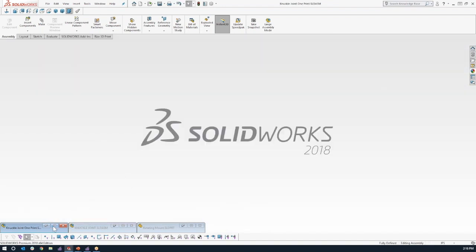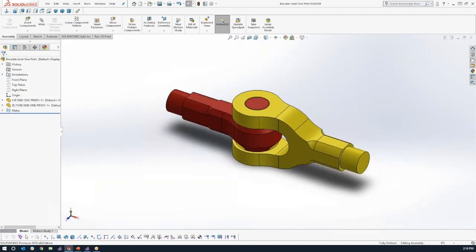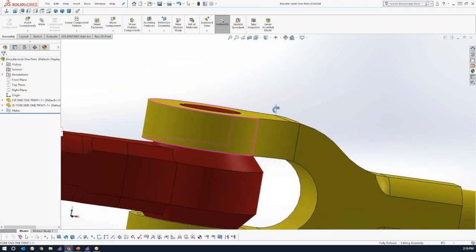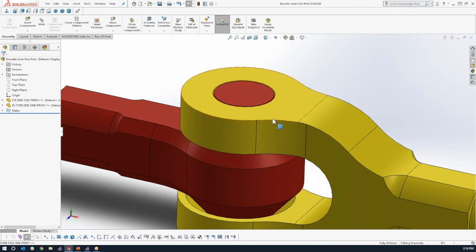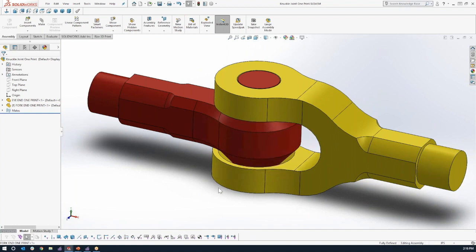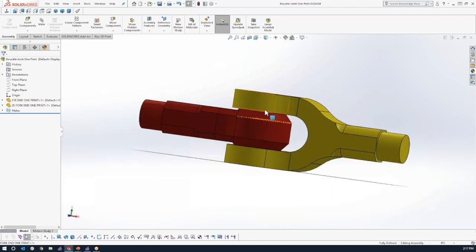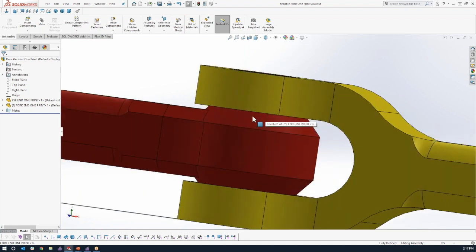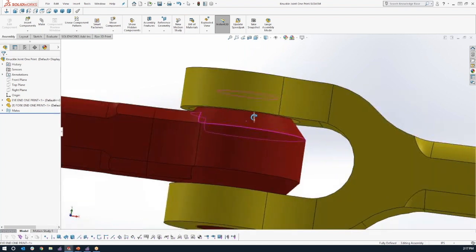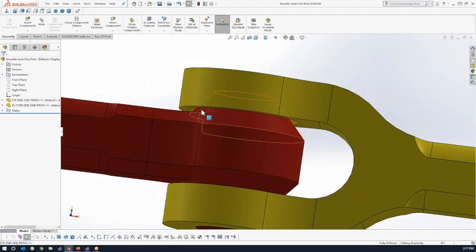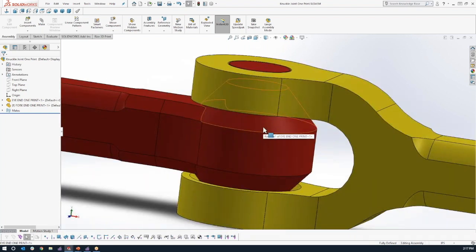Another approach is actually to design them so that you can print these parts as a single piece. Not only will it reduce the number of components that you're using, but you'll be able to print it in its flexible form right off of the build plate. What I've done that's different from the previous version is that I've made these surfaces here, rather than being all flat on the bottom, angled, and this allows them to build without filling the inside with support, which would be challenging to remove.